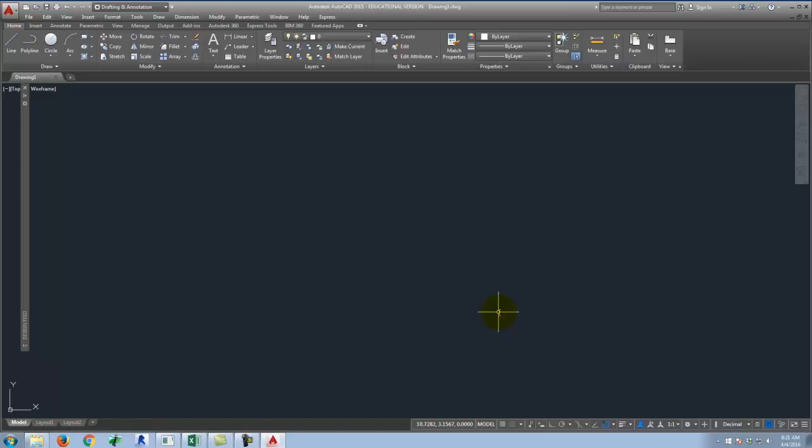Okay, so we're going to start in part 1. Today's handout is extraordinarily scripted in the beginning, so you can follow along with me, but if you get lost, you can follow the steps. We're going to start drawing with the Polyline tool, which is available right here. Notice that if I hover over it, it gives me a little extra information about how the shapes work. For right now, I just clicked the Polyline tool. I can see in my command line that it says P-line specify start point. That's where I'm going to start, and I'm actually going to type in a value on my keyboard.